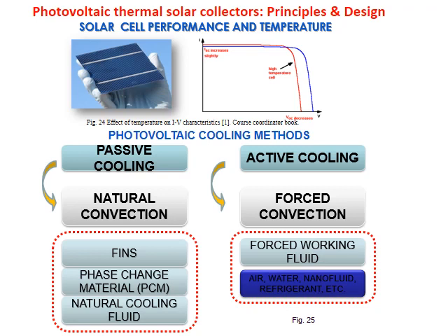Now this is the cell. If we plot the IV characteristics as we discussed before, this is how it looks. Now when the temperature of the cell increases, its voltage, as you can see here in the red one, decreases. And when voltage decreases, power decreases, energy decreases, efficiency decreases, everything decreases. Okay, we need to cool it.